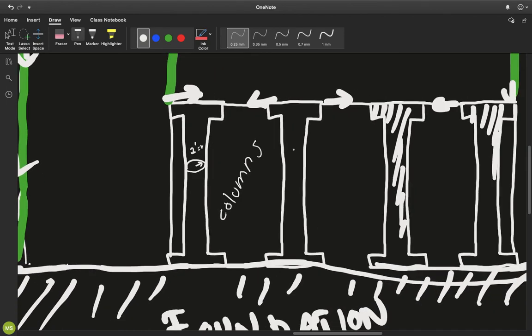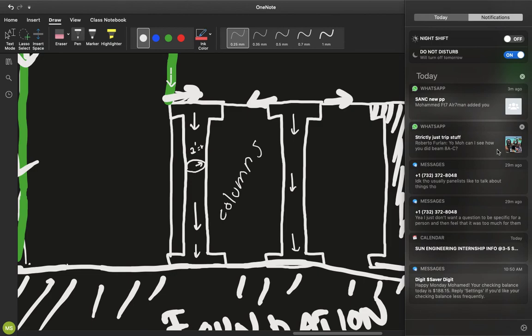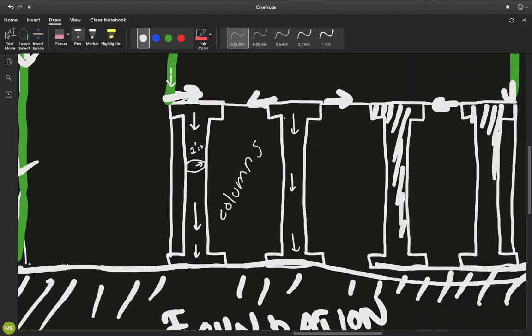And so this is going to hold a massive amount of weight because it is extremely strong. And now all of that weight from the snow is going to transfer from here into these beams over here, okay, and down into the column. And this column will take you straight down to the foundation. Straight down to the foundation. Like so.